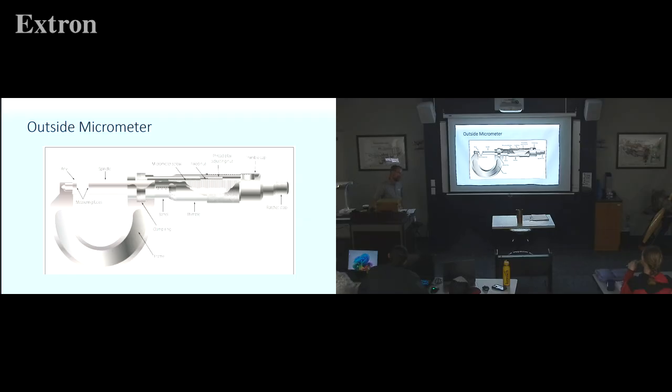So, I was just not thinking, so you know how when you said, for like the 1 to 2 inch one, you don't have that feeler gauge because you can just move it all the way to the end? Why couldn't you with the 3 and 4, since it still has that gap, just move it all the way until it stops? You know what I'm saying? But what's gonna be set at 3 inch then? How do you know that the barrel's set at 3 inches perfectly? It's not touching each other, see? There it is, right there. That one's all the way down to the very end. But who says that barrel's set at 3 inches? Oh, yeah, I see, okay. So I gotta grab a 3 incher, shove it in there and say, yep, that's it. Okay, I see.